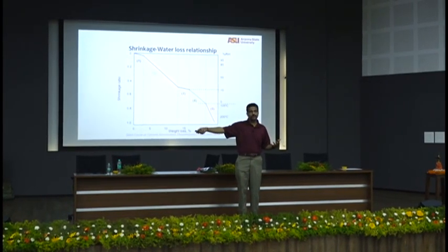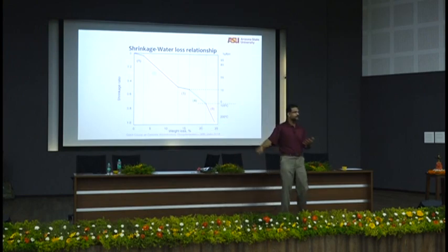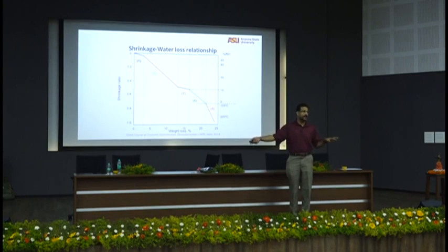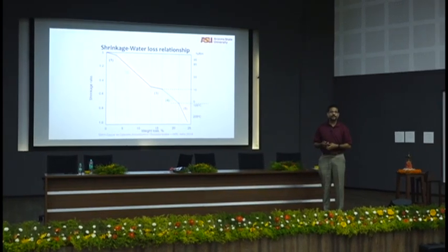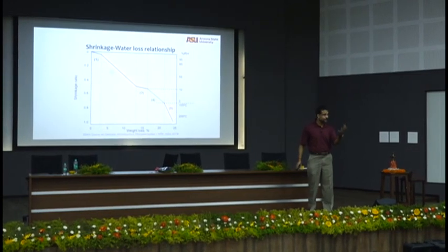Now, there will be some beautiful contractors who can make it crack, but if you're reasonable, it's very unlikely those concretes will crack, provided you give them reasonable joints. Okay, I'm not saying that you can put in a slab 5 kilometers long and it won't crack. No, you have to put in reasonable joints at reasonable spacings. It's very unlikely to crack because of shrinkage.